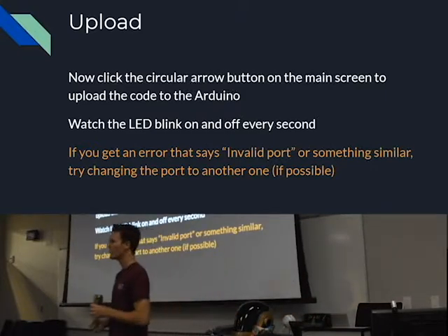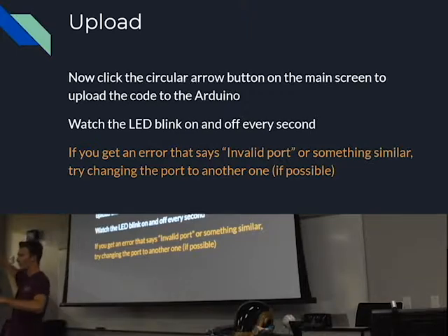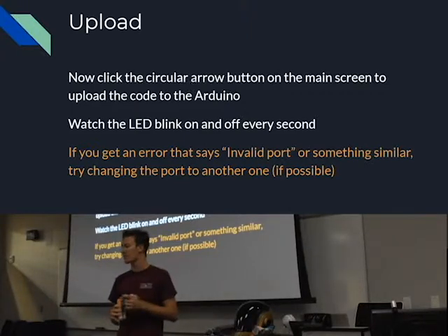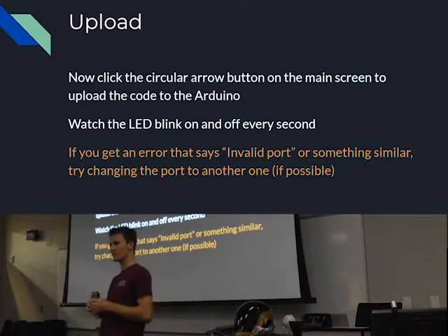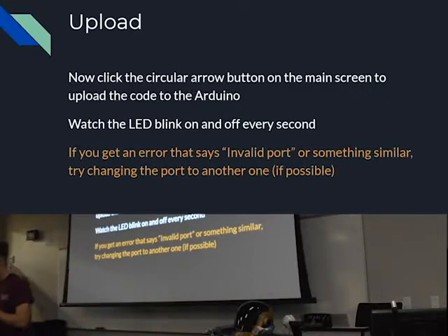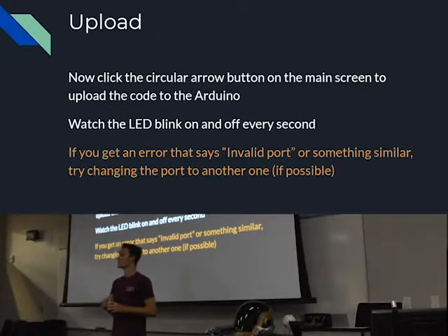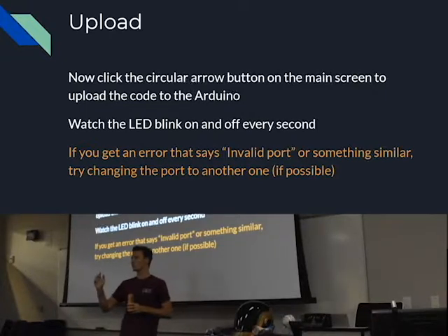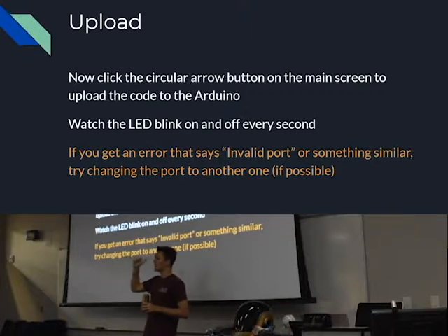Fine. So if everyone takes a look at the code, if you maximize that screen and look at your code, in the void setup method there'll be one line. pinMode, LED_BUILTIN, OUTPUT. Pin mode is setting up the pins, so anything that usually is in or out of the Arduino, you have to set up with pin mode, and you usually do it in the setup method.